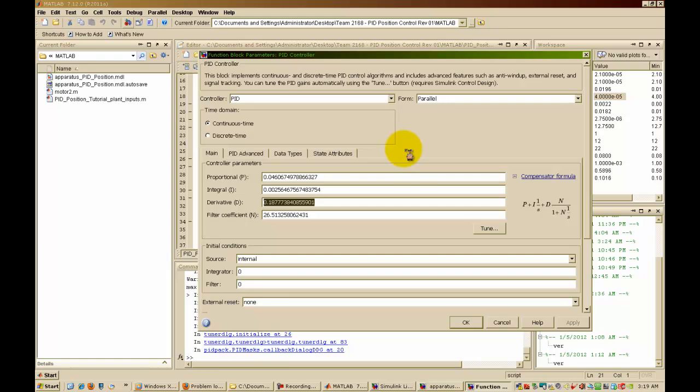Try to remember to set your steady state error to a number greater than 0. At a minimum, the value should account for the minimum error between your encoder ticks. Make sure you choose an encoder with a count that will provide you higher precision than you need. Also, make sure you're sampling the encoder value fast enough to feed the PID loop. If you don't sample it fast enough, you'll get a jerky response, because your set point position will be trying to compare to a very slow current position, and you'll notice a jerky response.